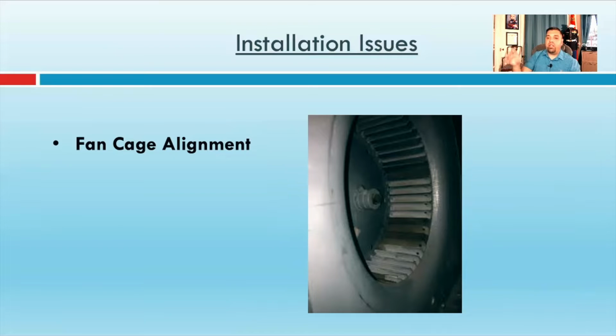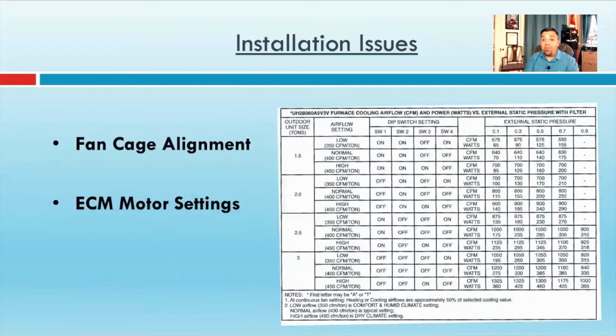And testing and balancing a system without fixing this first isn't going to help you, all right? So fix that cage alignment first. Obviously, verify the ECM motor settings.